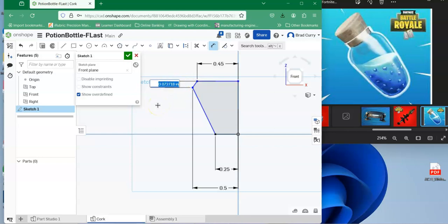That's what I wanted. And let's make this 0.05. Kind of bringing that in. It shortens it down, a 50 thousandths chamfer on that. I don't like that. So let me hit the escape button, get out of the dimension tool. Let's change this back to 0.1. So there we go. And let's also dimension the overall here with this.